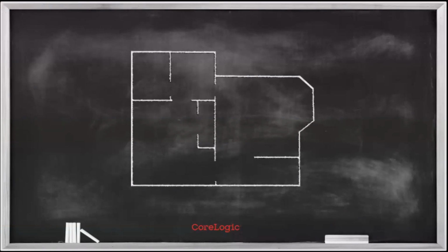But the reason I bring that up is because one of the things that I get a lot of questions about is the establishment of a drying chamber. Am I establishing my chambers correctly, right? Is this one chamber? Is it two chambers? Is it three chambers? And what you have to look at to understand how many chambers a given area really should be is the ease at which you can circulate air between rooms.